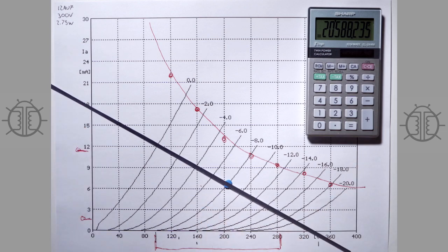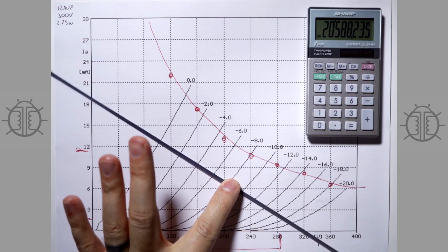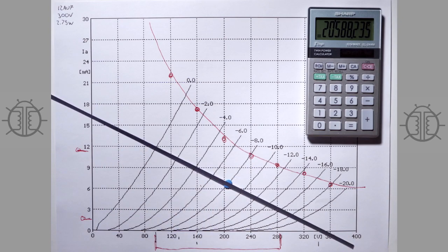And so this is another interesting thing that I guess we should talk about at this point. I was trying to say earlier that the load lines here represent a lot of different metrics. The gain of the tube, the intrinsic gain of the tube, is its gain into an infinite impedance.